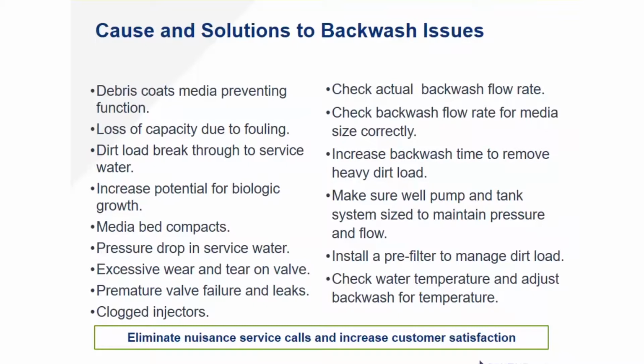If you're apt to think about that freeboard at the top of the tank as a waste, you would be incorrect. That space at the top of the tank is very, very tempting to use, but you don't want to use it. It's there for a design purpose. So you can fill a tank up to where you need to be in the tank, but don't overfill it. If you overfill it, you're going to end up backwashing excessive resin out to drain anyways, or causing issues or losing capacity over time because you can't get a good backwash.